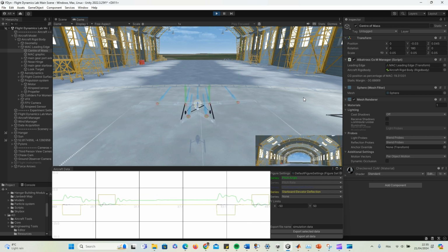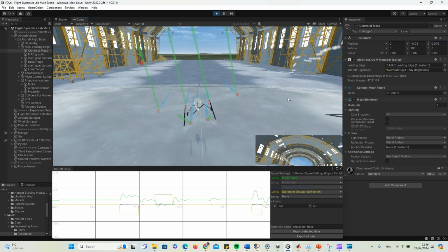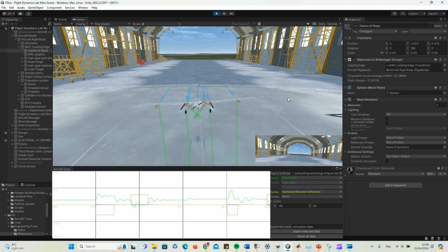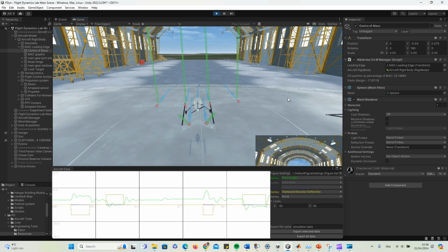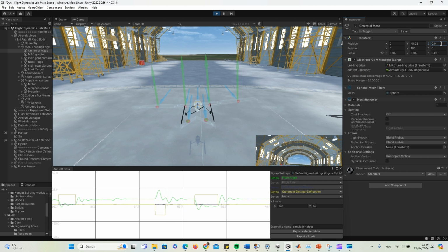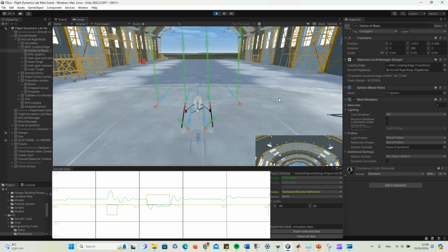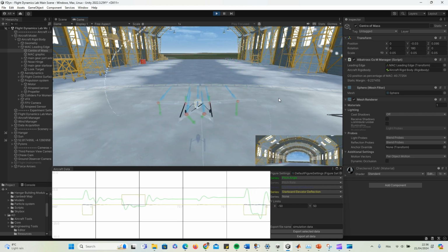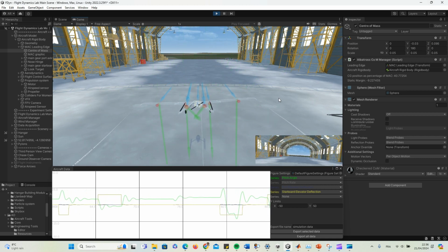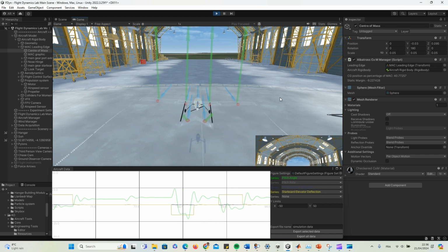However, there is a limit, perhaps at around 32% of mean aerodynamic chord, with the CG being placed there. The aircraft is just barely stable enough to control, and putting the CG any further back will, as will be demonstrated, make the aircraft very unstable and uncontrollable, whereas pitch control makes the aircraft forcefully roll, and it makes it rather unstable for the pilot to fly.